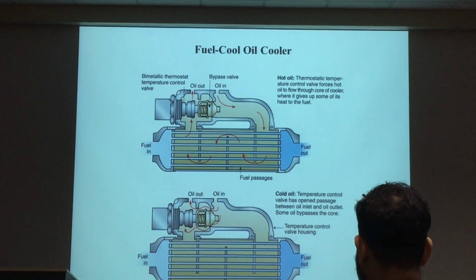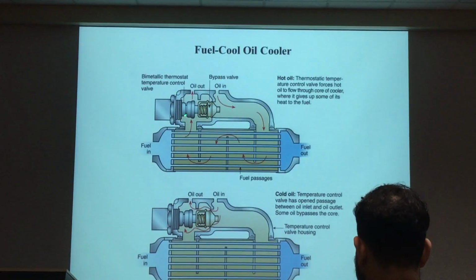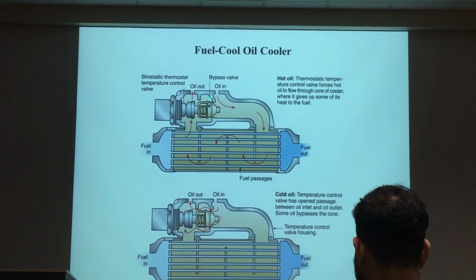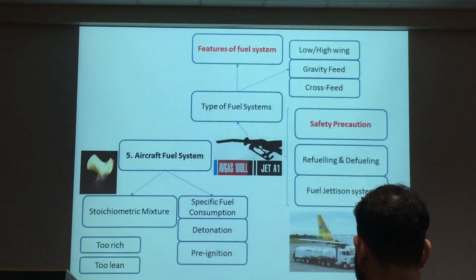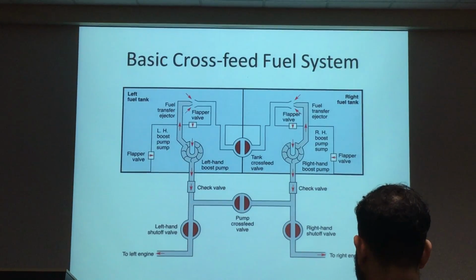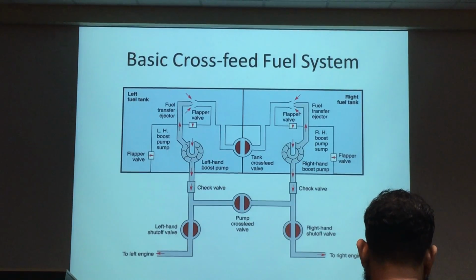But it's a spring loaded check valve. You allow one way flow. The other way cannot. This way flow to here cannot. You always must get out here. But because of the spring, there is a minimum pressure required before you bypass. So the idea of a check valve means one way. That's why you're driving your arrow side one way. Okay, this is what it means.